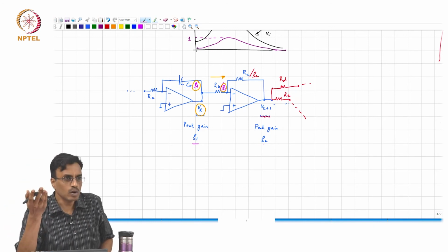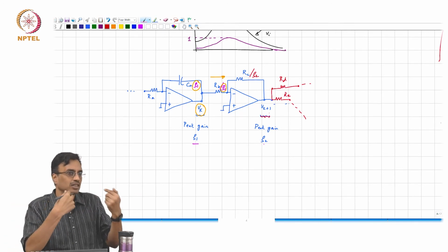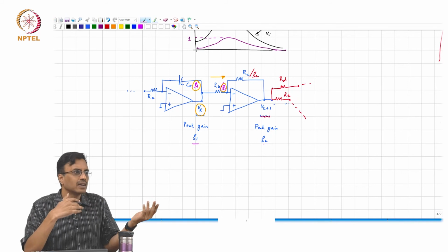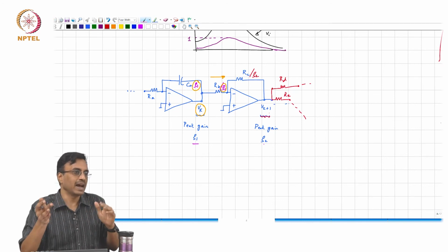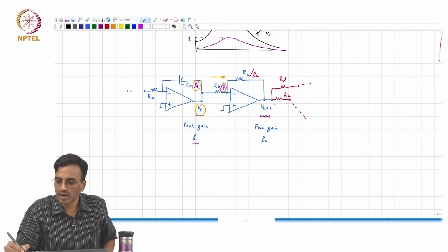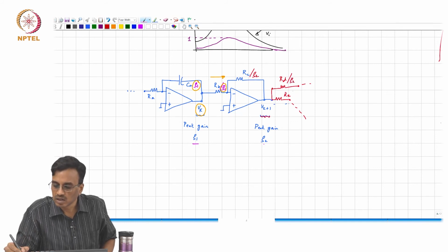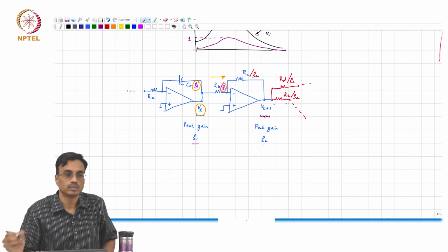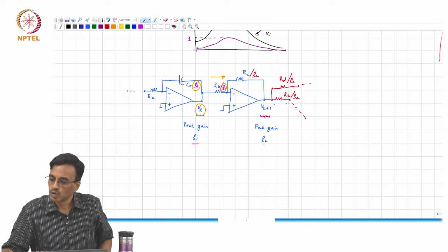And then what do we need to do? All the other resistors that are sensing this voltage should know that the voltage has changed. The current through them should remain as it was before, right? So what comment can we make about RD and RE? Both of them should be divided by G2. Right? Okay. So in general,